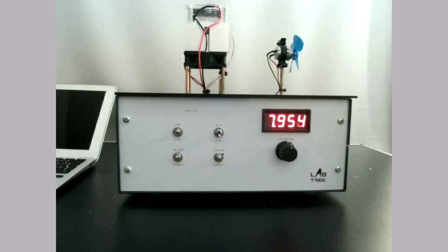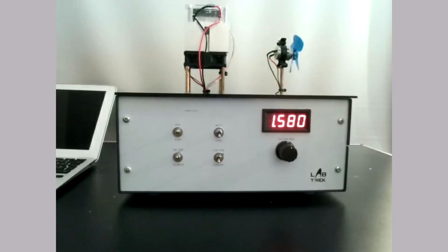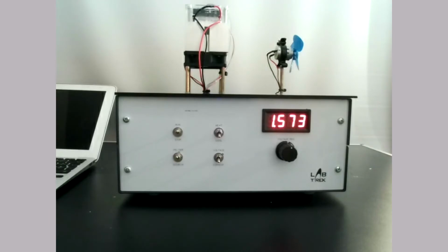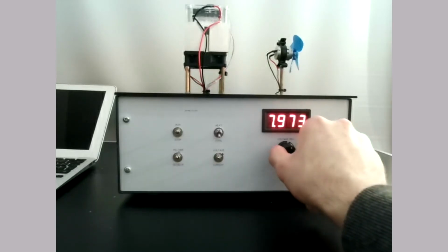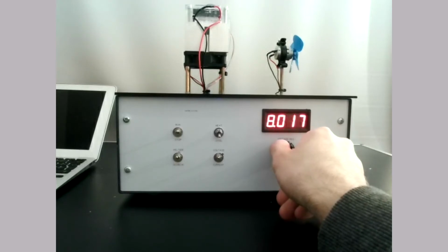The LCD display shows the voltage across the Peltier cell, or the current. With these two measures, it is easy to calculate the electrical power supplied, and evaluate the efficiency of the refrigerating system. By adjusting the voltage, it is possible to make a transformation, slow enough, to be able to see the supercooling phenomenon.